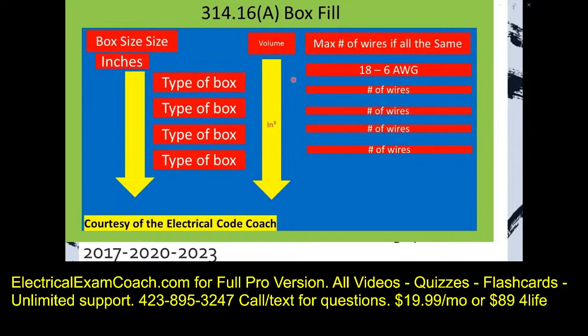We have 4 by whatever the depth is. In this column, you're going to find the maximum that you're allowed to fill each box. Then when we come over here to the far right of the table, it's one of my favorite pieces. It's actually like a cheat sheet. If all of your wires are of the same size, you can use this part of the table and make it very simple on yourself.